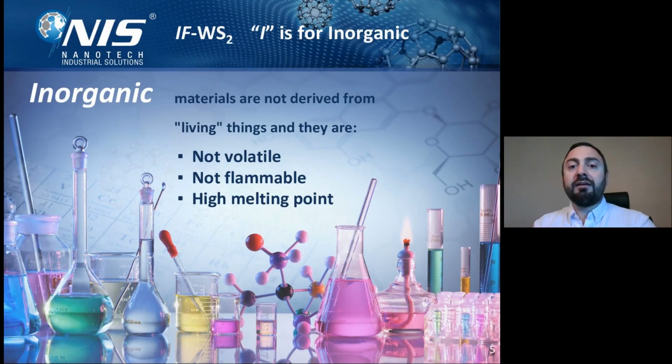So inorganic means that it's a mineral material. Most inorganic materials have a high melting point. They don't degrade. They're not biodegradable. One of the examples could be salt. It could be environmentally friendly, but it doesn't mean it's biodegradable. So there are two terms, biodegradability and environmental friendliness. They shouldn't always go together.